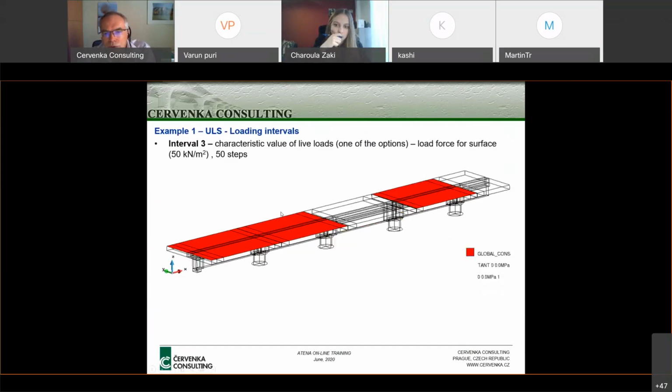The live load, of course, can have different positions depending on the load combination. So this, for instance, shows one of the combinations, which in the end showed to be the critical one. But in practical situations, we have to estimate maybe several of these load combinations. One which would be full load everywhere, or maybe every second span is loaded.